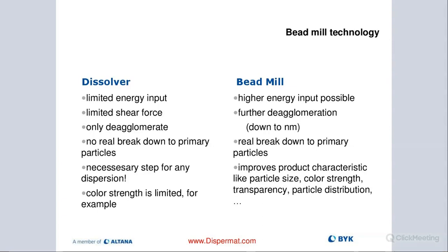It's really almost impossible to do without some sort of media. And it is a critical step for any dispersion process that you properly pre-disperse. If you don't pre-disperse and you go straight to a media mill, let's say you start out with 100 microns or 80 microns, and you go to a horizontal bead mill, for example, you have a screen, depending on the manufacturer, or you have a dynamic gap, and there is a size that basically allows the beads to stay back in the milling chamber and everything to circulate back through the milling chamber until you're reducing your particle size to the appropriate size.